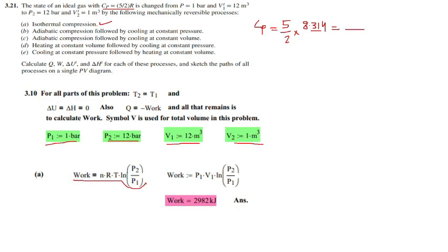You know that PV is equal to nRT. So that's why I have written here P1 V1. The value of P1 and V1 is given. Always use the absolute units. Convert 1 bar into Pascal, which will be equal to 10 raised to power 5 Pascal. So you have to put the Pascal here. If you put the Pascal here, you will get your answer in joules. So your answer will be 2982000 joule. You always use SI units, so your answer will also be in the SI unit.